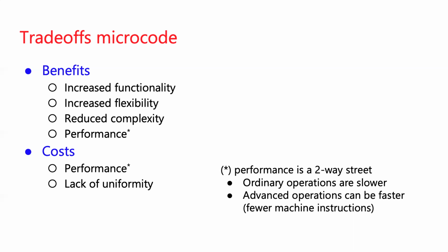If every machine instruction that you run requires you to go run a little sequence of microcode instructions, then that seems like more overhead to running that instruction. If, say, an add or a multiply requires going and running a little subroutine in microcode, then looking up that subroutine and running all the little microcode instructions, that's a lot of steps.